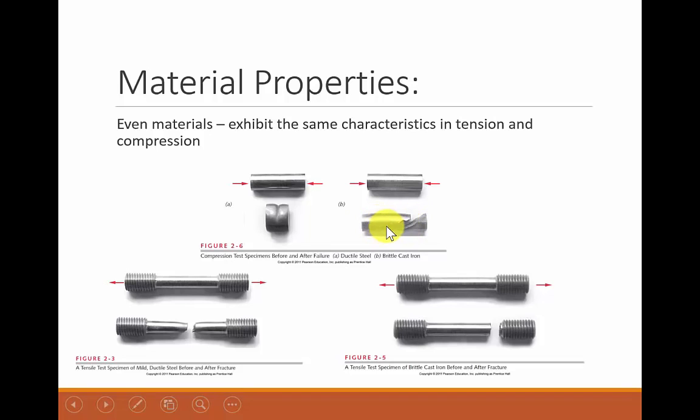And again, what's really interesting about this failure line is now this failure line seems to be on the 45-degree. So we'll spend quite a bit of time talking about failure mechanisms. But I just want you, as we're looking at these pictures, to start considering more than just that it failed or even what shape, but start thinking about maybe why it failed on a 45-degree axis in compression, 90 degrees in tension. It doesn't fail in compression, although this is no longer a useful part, I don't think, and failed 45 degrees in tension.